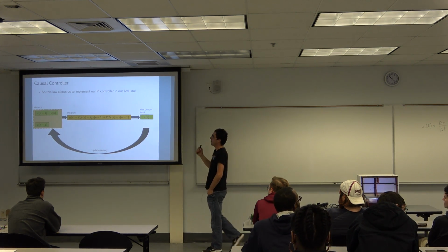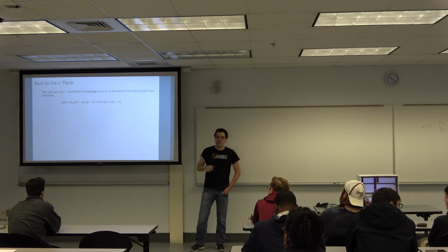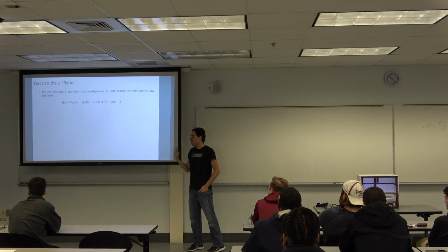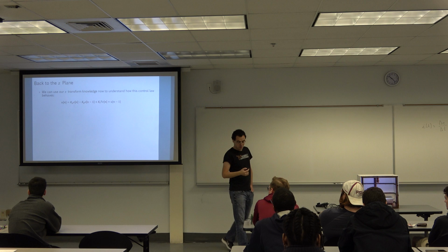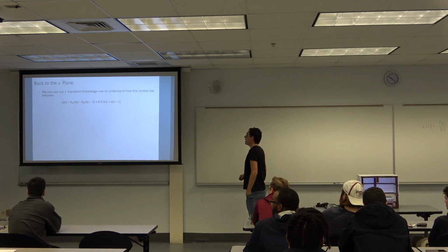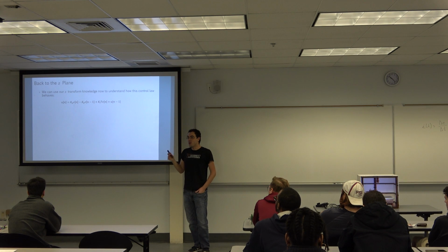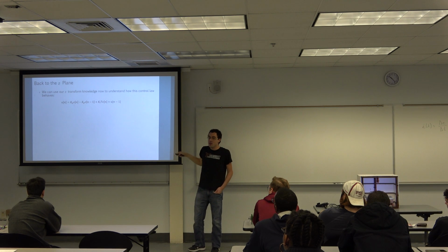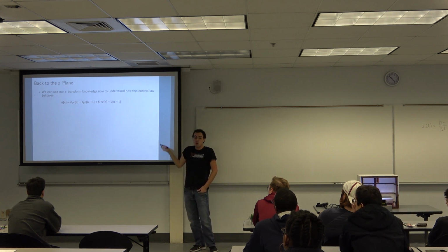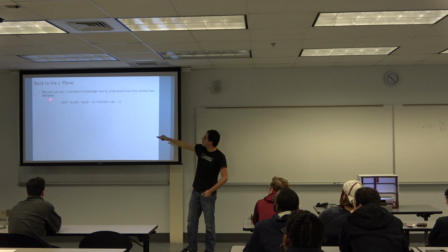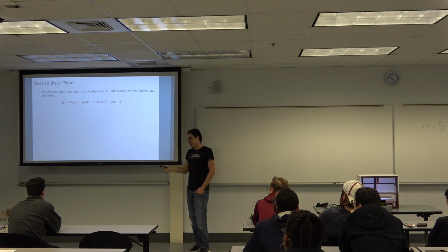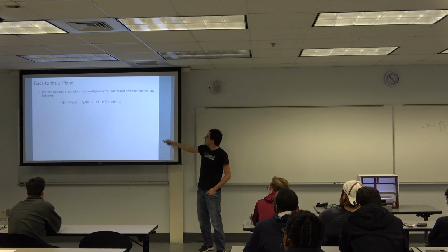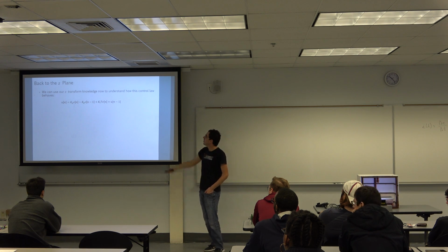Okay, so now we went through the implementation details, and now we can do some analysis. So we have the discrete-time version of our controller, and we can use the Z transform, our new fancy tool, to analyze it. It's kind of difficult, but you can realize that the Z transform of this expression would give us the Z-plane behavior of our controller. And in this case, the Z transform of u(n), similarly to the Laplace domain, is just capital U(z). Similarly for e, it's just capital E(z).